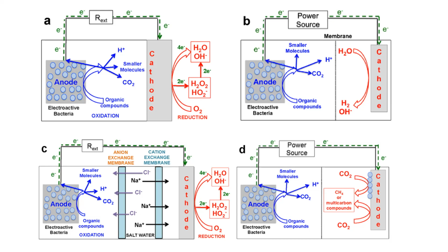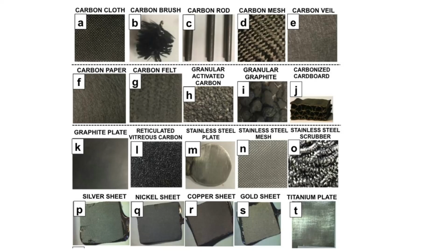The anode is an essential constituent of a microbial fuel cell. It plays one of the greatest roles in increasing power density. Anodes are a key determining factor that influence microorganism adhesion and electron transfer. This is an example of a low-cost material, made from carbon. In general, a good anode should be biocompatible, highly conductive, with high physical and chemical stability, high specific surface area, and high porosity and non-fouling properties for microbial adhesion and biofilm formation.